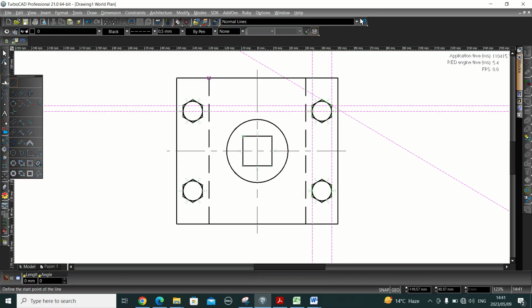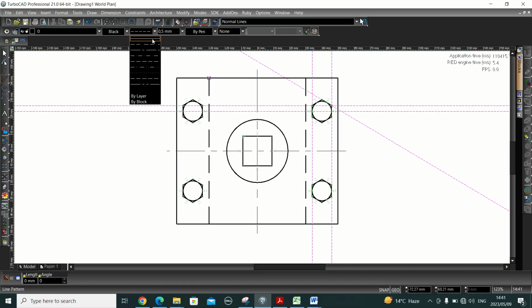Now let's draw this one first. Go to your line tool, make sure it's selected. Change that, we need a solid line. Click on the solid line. Press tab. Now we need to define our x. We said it's 5. Our y, it is 44. Press enter, starting from the top. Now we need to deactivate this snap because I want to click exactly here.